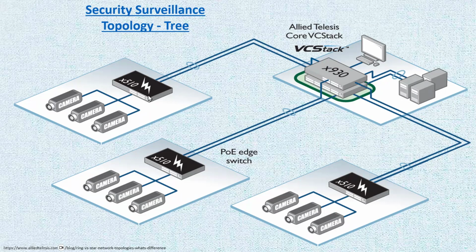And when you have a larger facility, you can have remote switches. So you will have one switch placed in some sort of area. Into that switch, you would bring the cameras and plug them in. It is recommended that those switches are PoE switches, with the possibility of power over Ethernet. This way, you just plug in one Ethernet cable, and it's powered with the PoE.